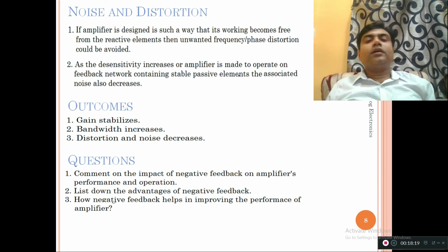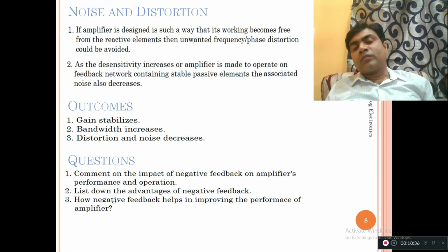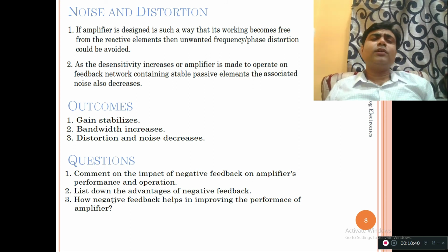Now, as I already discussed, if you make the feedback network entirely dependent on the resistive values, and you don't apply reactive components like inductor or capacitor, there is no change with respect to time. If there is no change with respect to time, your linearity will increase. If the non-linearity is decreased, the distortion is definitely going to be decreased.